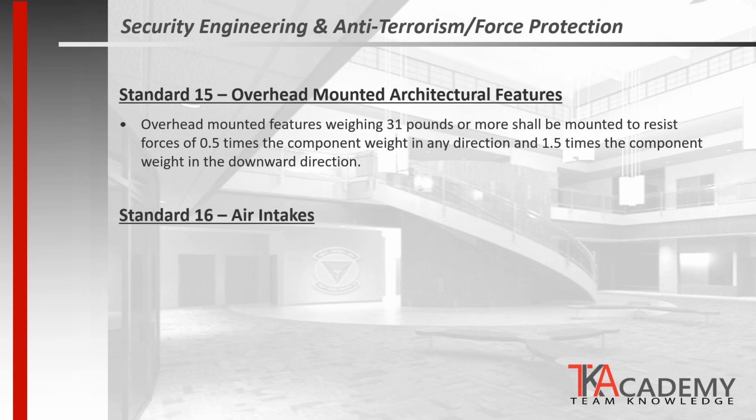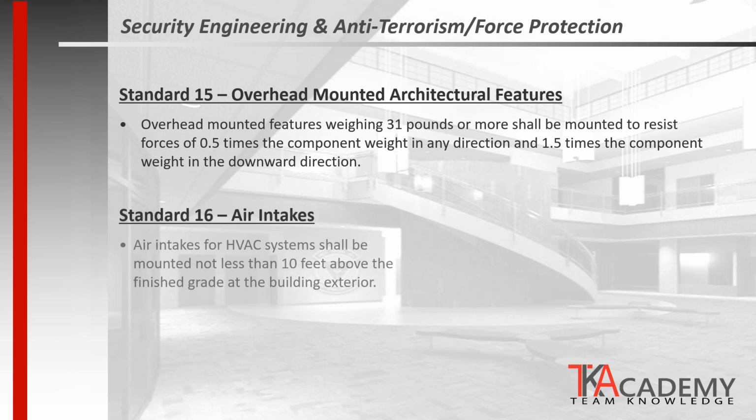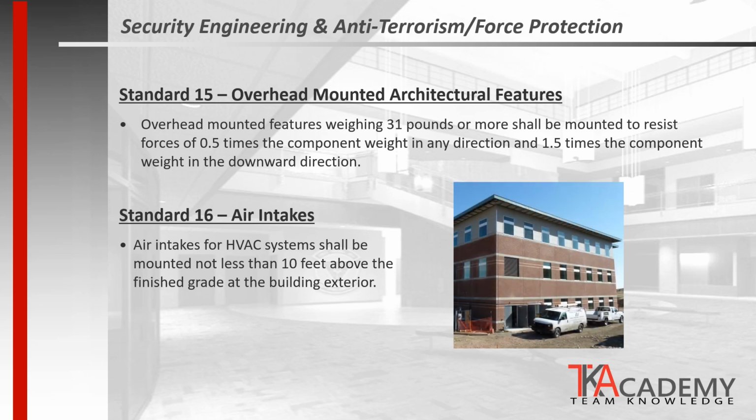Standard 16 addresses air intake. It states that air intake for HVAC systems shall be mounted not less than 10 feet above the finished grade at the building exterior. This is to mitigate the threat of someone placing a toxic or poisonous substance outside the air intake that gets pulled into the air distribution system and spread throughout the building.